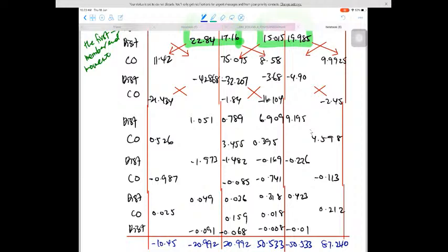In my next video, I will continue this example. I will show you how we use this moment to draw the bending moment diagram, because this is internal moment, and internal moment is the bending moment. Actually, the member end moments that we get from the moment distribution table, we can use straight away to draw the bending moment diagram without the shear force diagram. I will discuss that together with all of you in my next video.